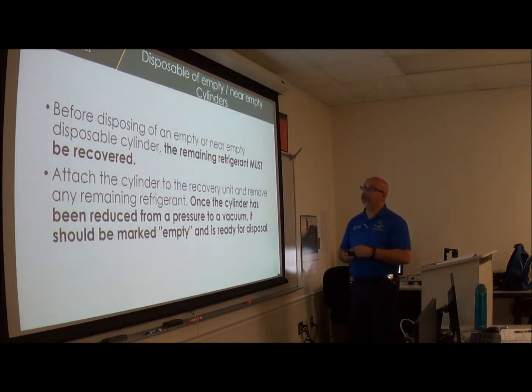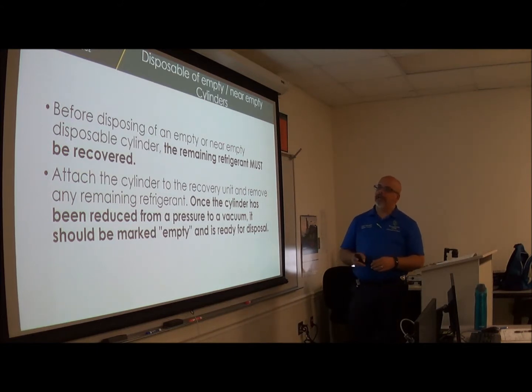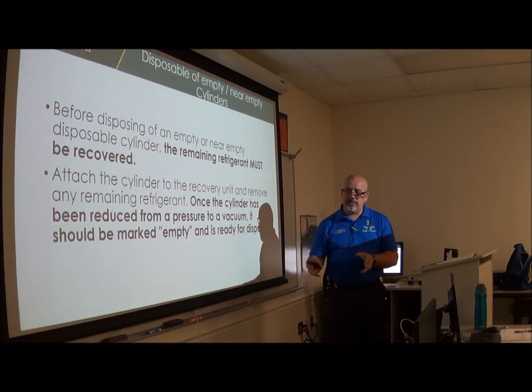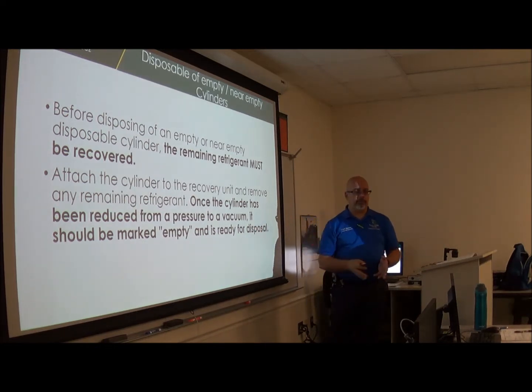Disposal of empty or near empty cylinders. Before disposing of any empty or near empty disposable cylinder, the remaining refrigerant must be recovered. Attach the cylinder to the recovery unit and remove any remaining refrigerant. Once the cylinder has been reduced from a pressure to a vacuum, it should be marked empty and is ready for disposal. So when we do this, it's the same thing we do with the vacuum in the vehicle to be able to put in new refrigerant.